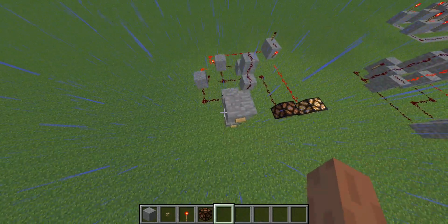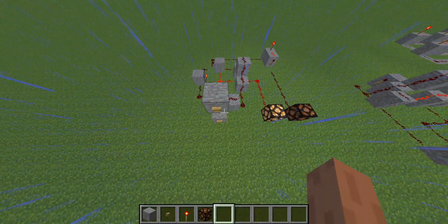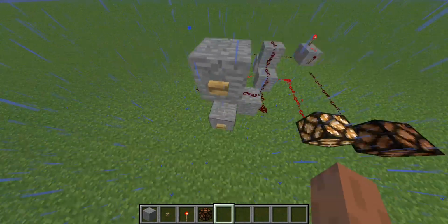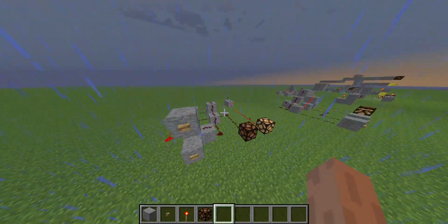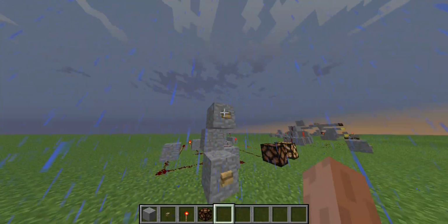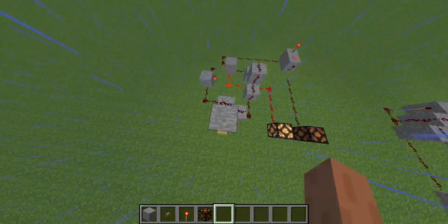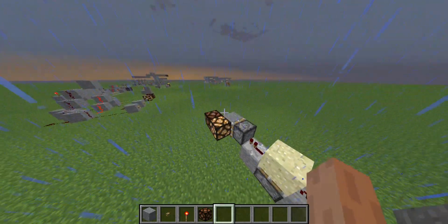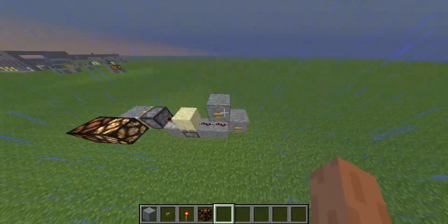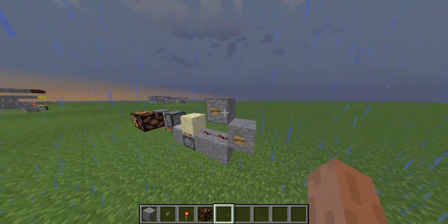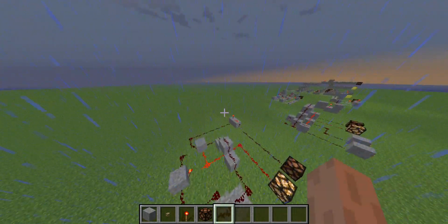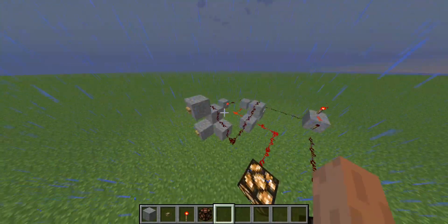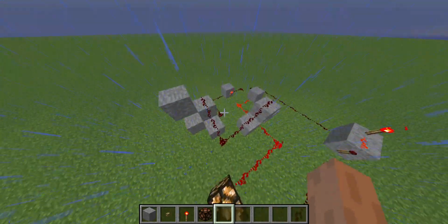For example, let's reset the first one. Okay? It doesn't permanently switch to it, because I can always just press this one to reset it or switch it. It's always like that if I do not press the second button, but with the T flip-flop, it's always changing. With the T flip-flop, I press either button, it doesn't matter, it's going to do the same thing. With an SR latch, I couldn't have just one input. I would have to have two, because there are two separate ways it's going.